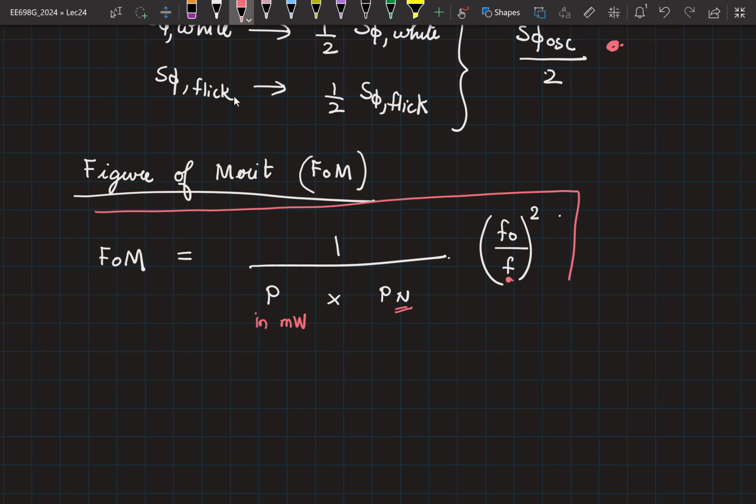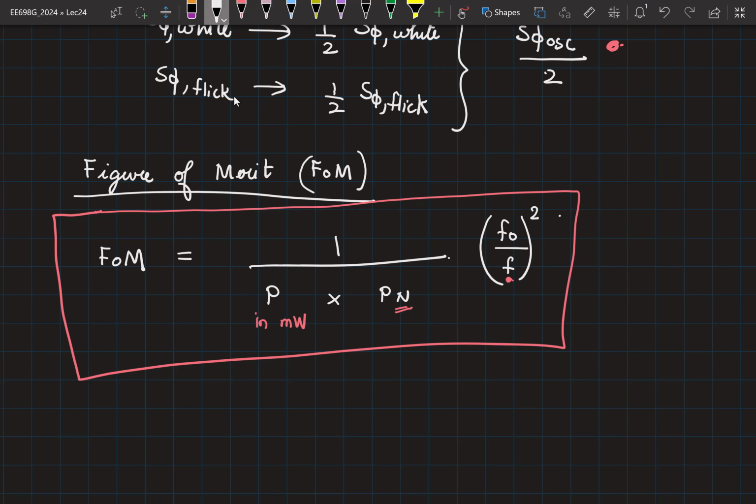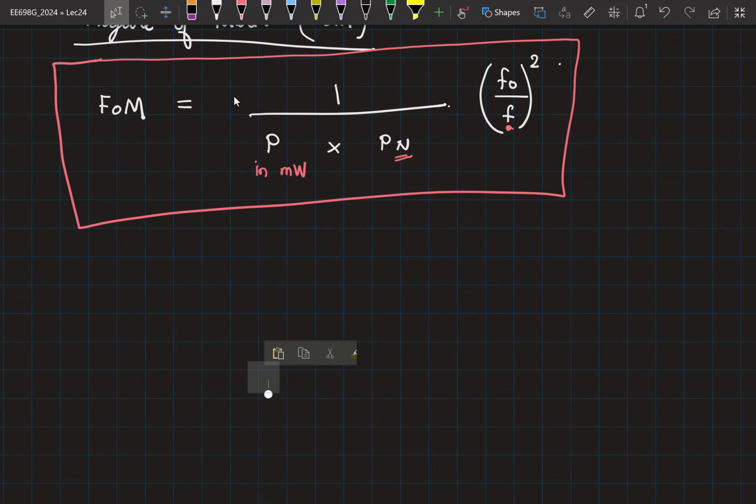So now in comparing the 4 architectures of the ring oscillator that we have come up with, we will directly compare for the FOM and see which of those architectures is giving you a better FOM. Okay, so let me quickly rewrite this equation so that it becomes easy to use the result we have derived so far.